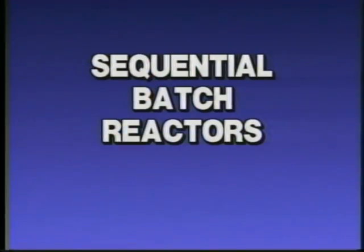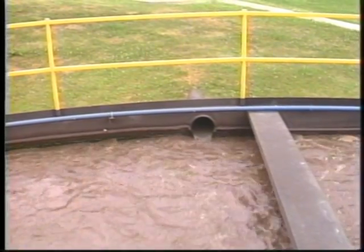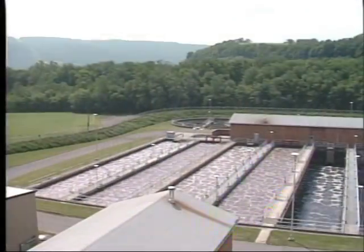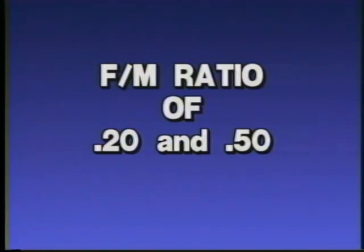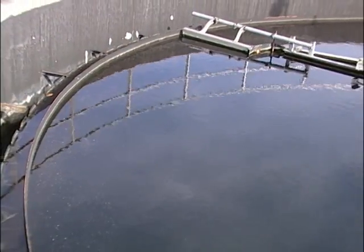In the conventional activated sludge facility, the wastewater enters the aeration tank at one end and exits through the other. In most cases, the influent wastewater has passed through the primary treatment before entering the aeration tank. The return activated sludge usually enters the aeration tank at close to the same location as the influent wastewater. The detention time in the aeration tank is usually 4 to 8 hours, with an F to M ratio between 0.20 and 0.50.